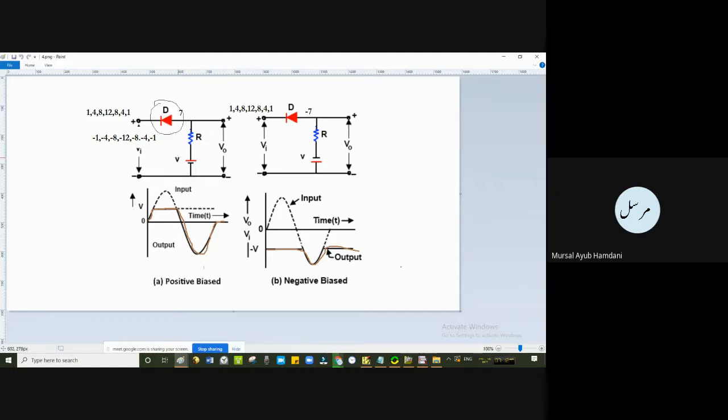Now if this supply voltage is 7, I can cleanly assume that with a little drop across this resistance, almost negligible due to the small current and small resistance taken here, this 7 gets directly applied at the anode, the positive side of this diode. So 7 is sitting always at the positive side of the diode.